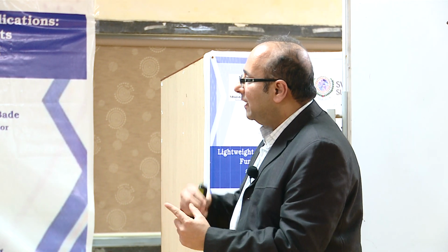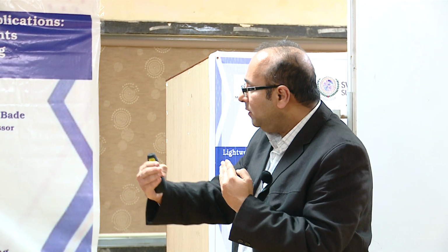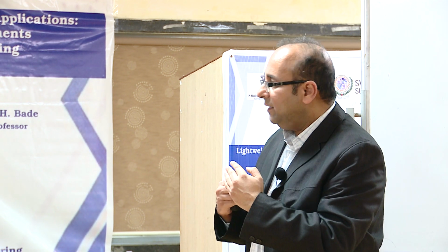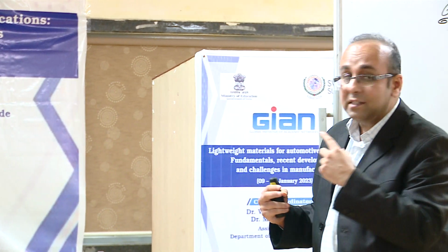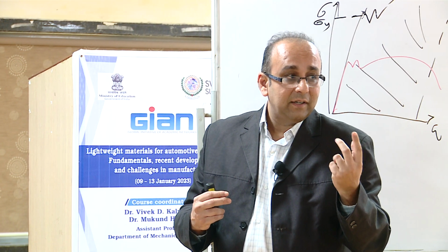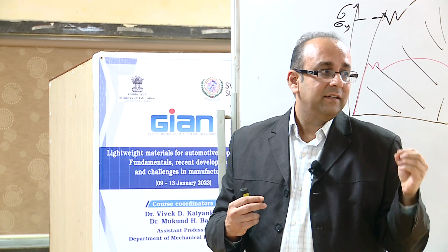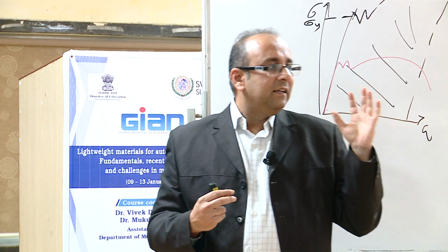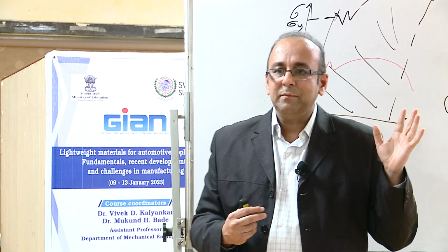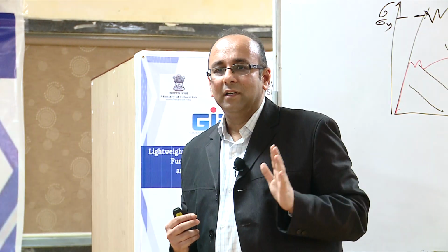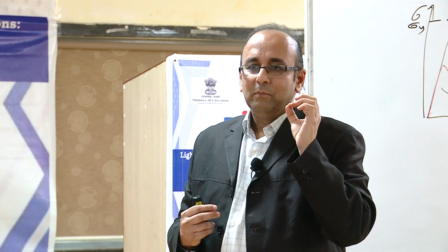So basically, either by controlled heating or by controlled cooling, we can have a second advantage of this hot forming, and that is we intentionally create different strength in different areas. That's why when I talk about this lecture as light metal, actually it is the wrong word. I would say material utilization.